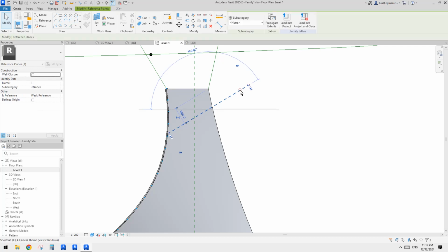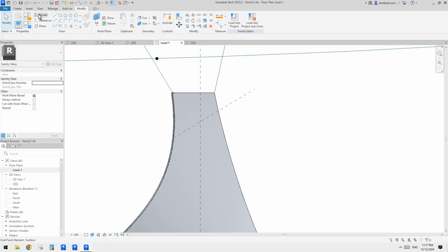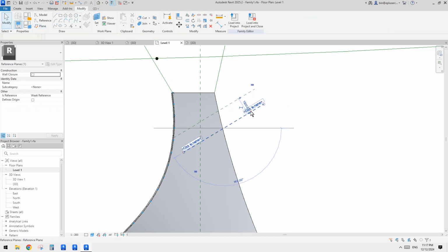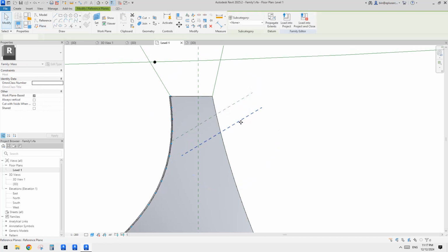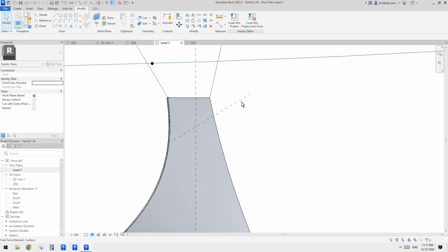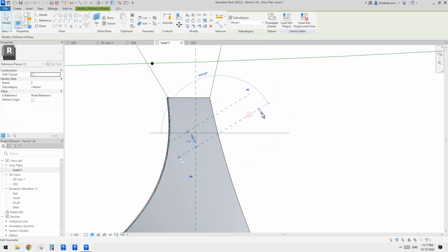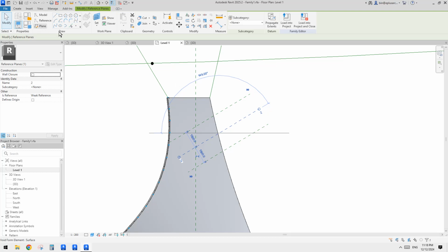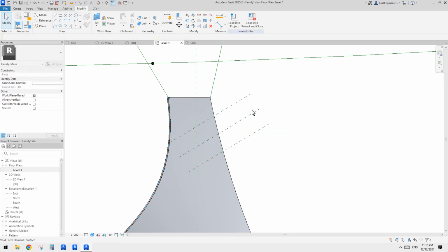Then we can just CS, create similar, doesn't work here. Pick 1500. Now let's, so it was, hang on, doesn't work. Okay. Offset, when we offset, it won't rename, but I'm pretty sure if we copy, Revit will rename this one, so we can say become 2. So copy is fine, but not offset, not create similar with offset. How about mirror? Let's try.